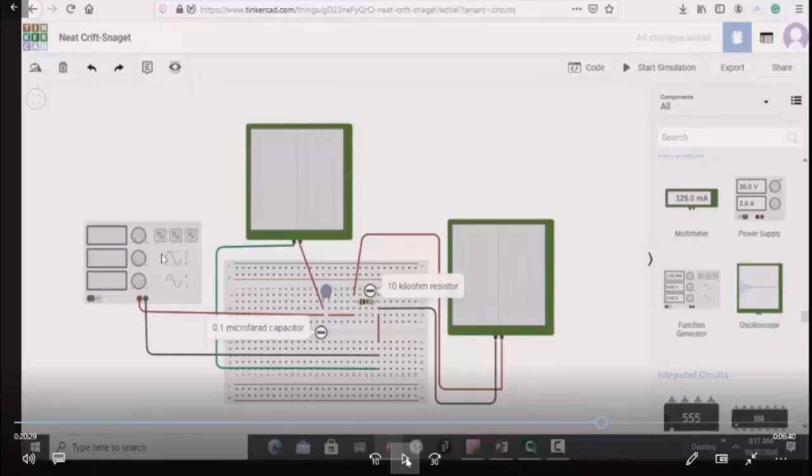So I know my cutoff frequency is say 3000 hertz. Then from somewhere from 1000 hertz to 3000 hertz, I'll take more readings. Say every 100 or every 200 hertz, I'm going to take readings till I reach some 3000 or 4000. After 4000, I know it's going to be a flat part.